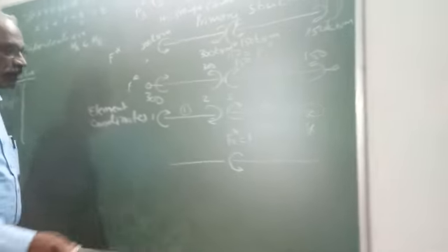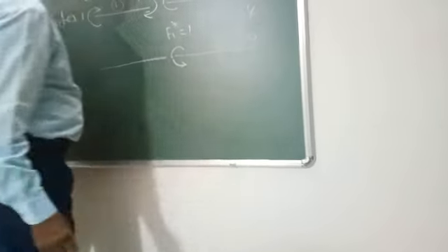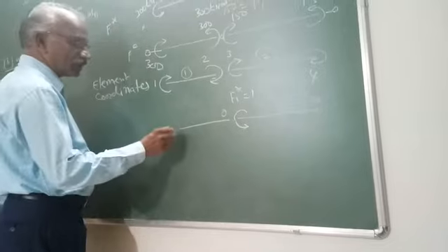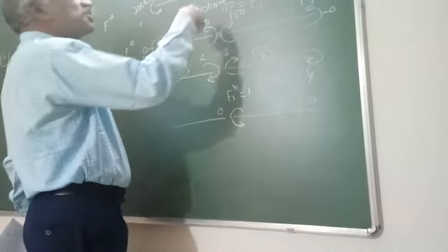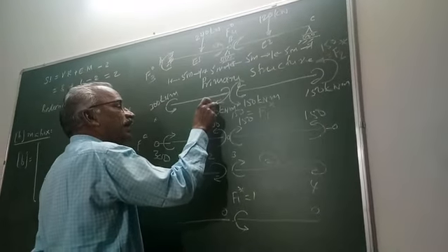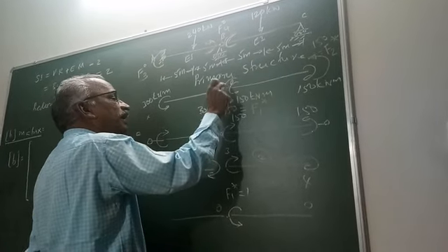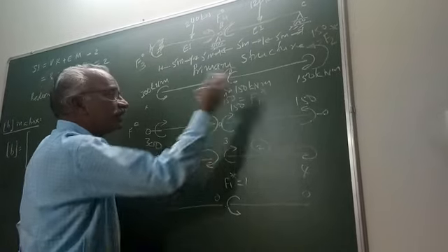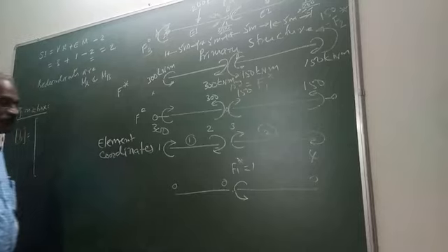Therefore, when we apply unit force here, at this end the moment will be 0, and this is a hinge here. Therefore, here also it is 0. It will not be carried over. We are applying in the span BC because the need is here only. Here it is 300, here it is 150, so minus 150 will be applied at the point B in the span BC. Therefore, F1 star is applied in the span BC, and here also it is 0.